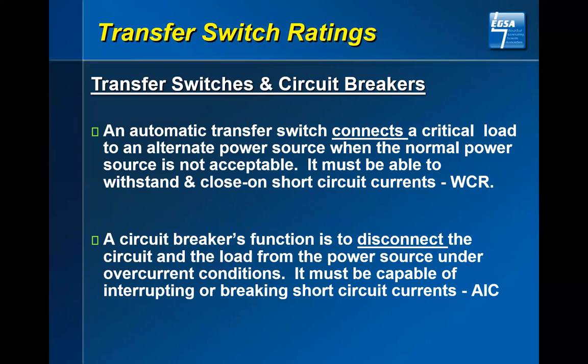As you go through your distribution to your emergency down to that transfer switch, I doubt that down at that transfer switch, you still have the capability of 65,000 amps. We have a little illustration in one of the other presentations that as you do that, we found out that there's really only 10,000 amps that could occur down at a specific transfer switch in the electrical scheme.